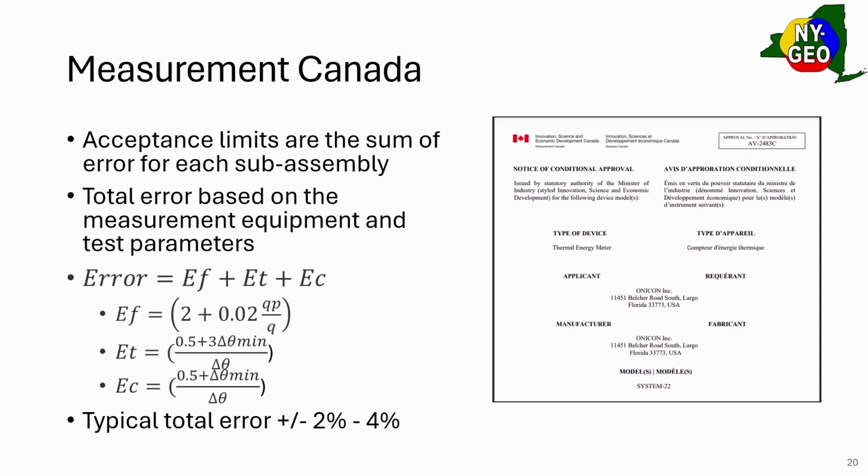Yeah, interesting question. The ultrasonic clamp-on, or both? Yes, both. So the ultrasonic clamp-on transducers come in different sizes. If you have a smaller pipe, the transducers are smaller. We'll get into small delta T considerations in a bit, and I know that's a concern of yours, but you can have a reasonable delta T on a small pipe too. You just have to match your flow rate with your pipe size and your system capacity. Great questions, and that's why it's good to retain this engagement here, because nobody wants to listen to me talk for very long. But we'll keep going.